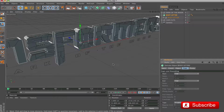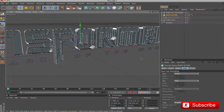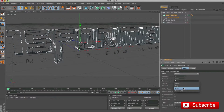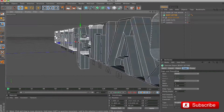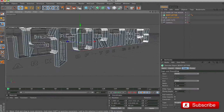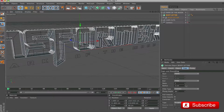Go to the caps panel, and insert none on cap start, and fillet on cap end. With radius to 4.25.